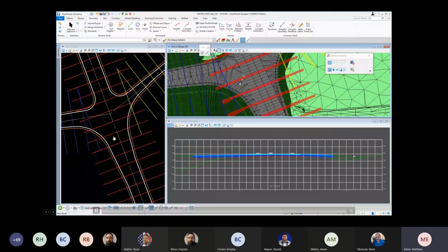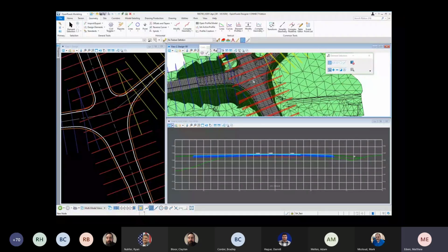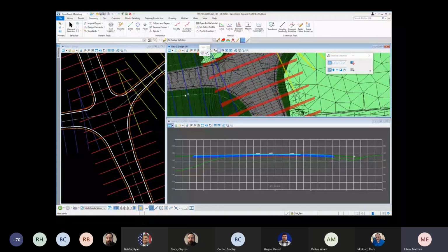Okay, so now I just want to go ahead and demo modifying a couple of these name boundaries just so we can look at what happens when we do it. In my view here, I have a plan view with the name boundaries, the 3D references attached for the boundaries themselves, as well as my 3D view, where we can see the name boundaries. In both of these instances, I used some level symbology overrides to change the color of these name boundaries just so we could see them easier for the demo.